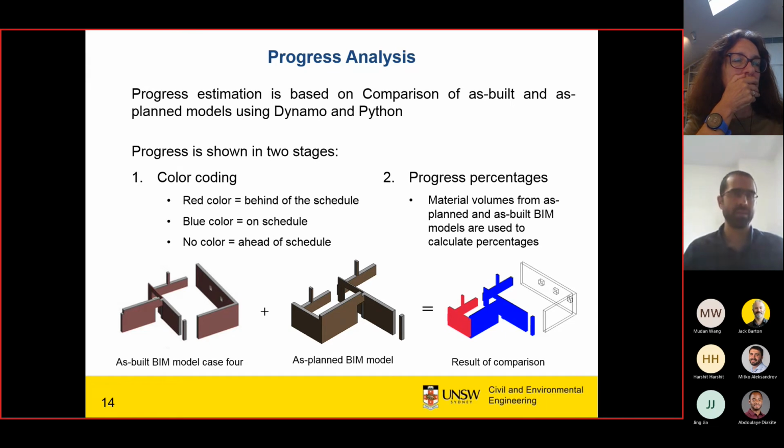I have seen different contractors, when they provide the schedules, front load the schedule. It means they will provide much more money for the early works. For example, the foundation will be first. They will provide a higher amount of money for the foundation. Let's say if the foundation is X amount, they will provide X plus 1 for that amount.